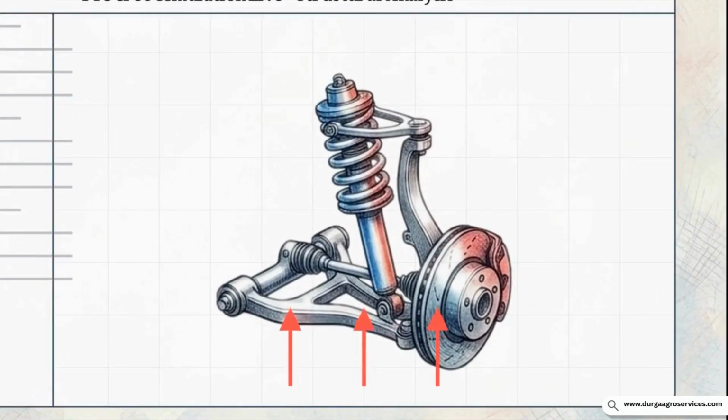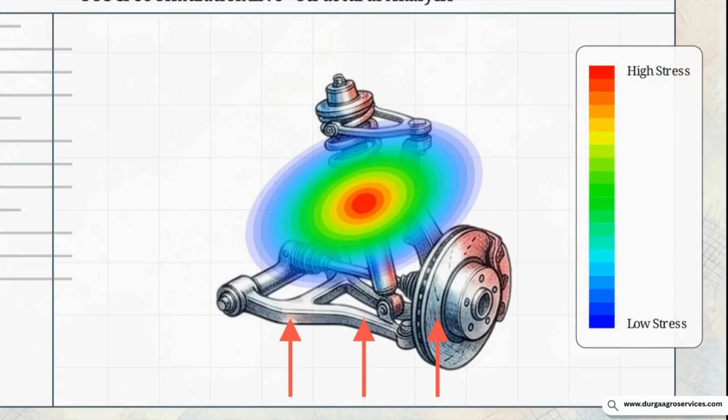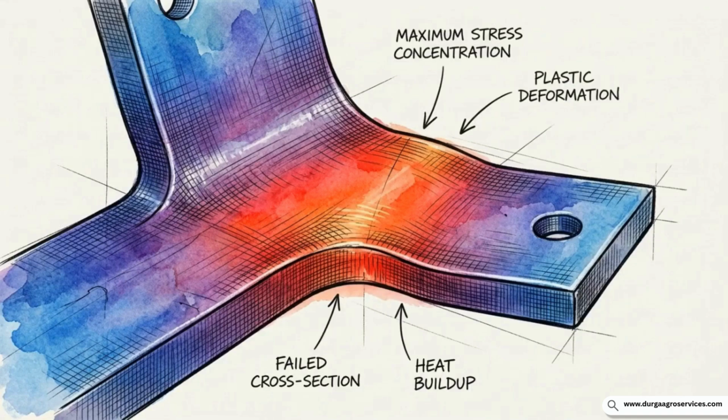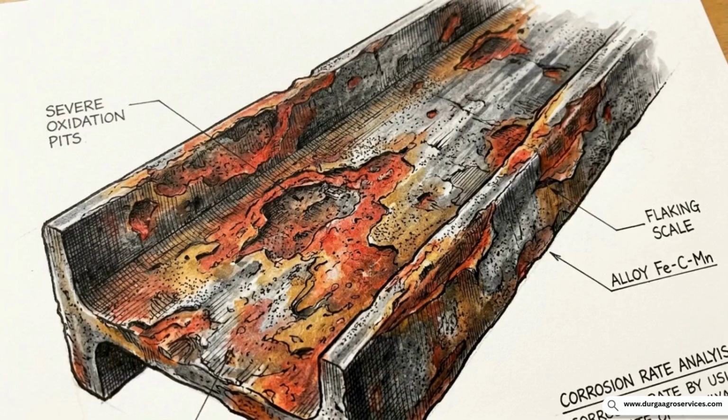As the red arrows push up on the hub, you can see a localized stress heat map blooming across a specific connecting bracket. By calculating exact displacement and safety factors, the system pinpoints the precise coordinates where the applied force exceeds the material's yield strength, causing permanent physical deformation. But surviving a single maximum load is only one metric. Materials degrade over time due to repeated stress, and we need to account for fatigue analysis.